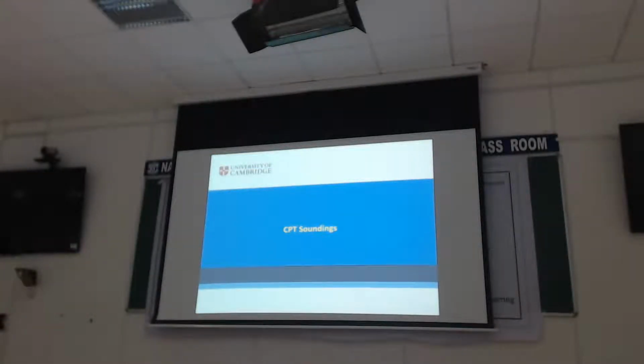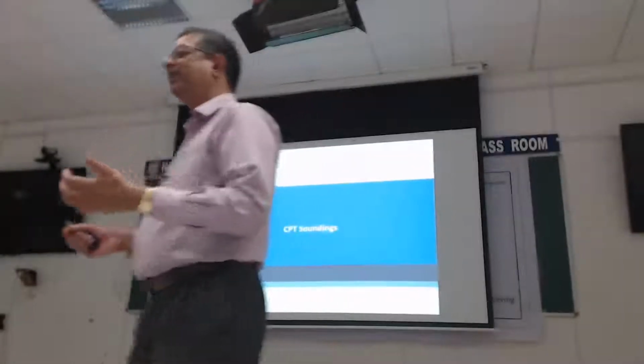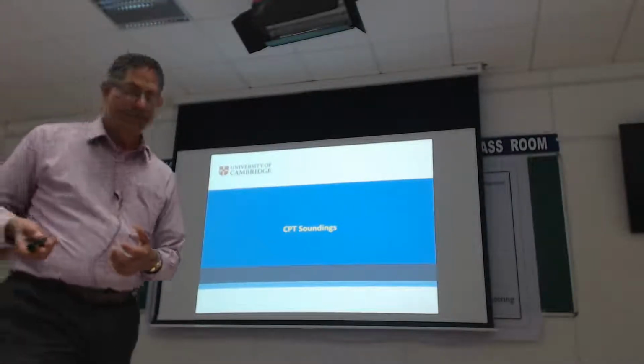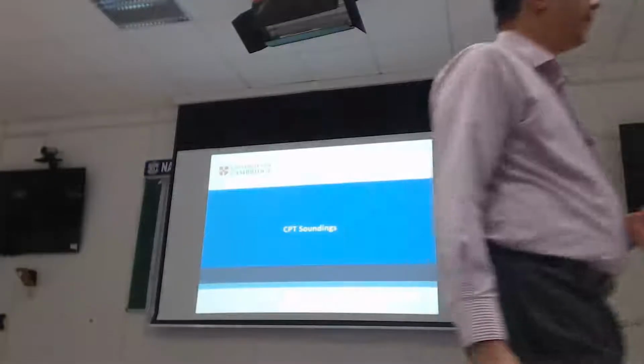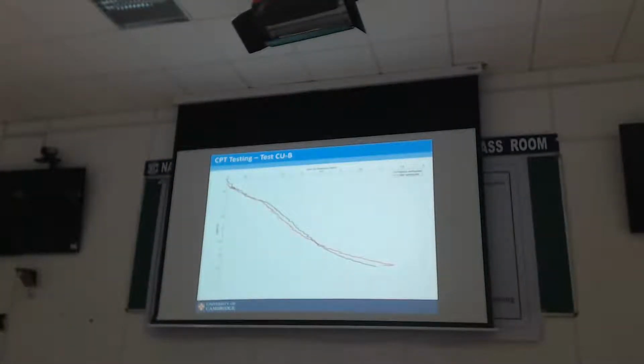As I said, doing the CPT was compulsory for both. So we said, right, we're going to do the CPT at 80G and 1G and see how the strength actually compares from these. So we've done the CPT. We do this twice, before any earthquake is fired and after the earthquake is fired.